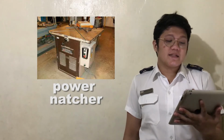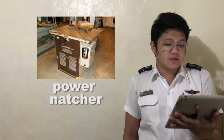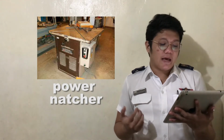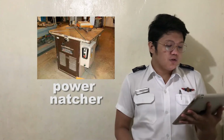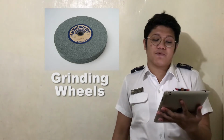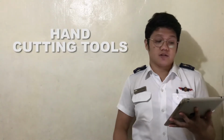The water acts as a lubricant for faster grinding while it continuously cools the edge of the metal, reducing the heat produced by the material being ground against the wheel. It also washes away any bits of metal or abrasive removed during the grinding operation. The water returns to a tank and can be reused. Lastly, our grinding wheels. The grinding wheel is made of a bonded abrasive and provides an efficient way to cut, shape, and finish metal.